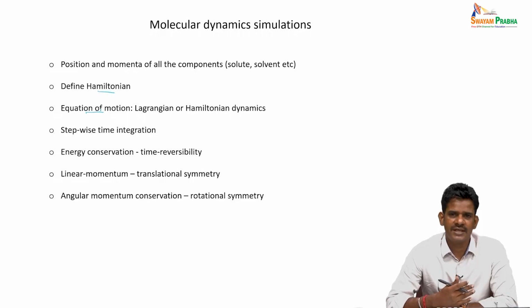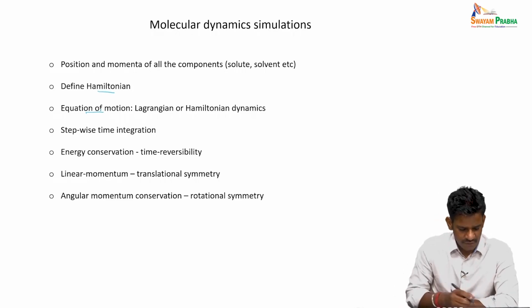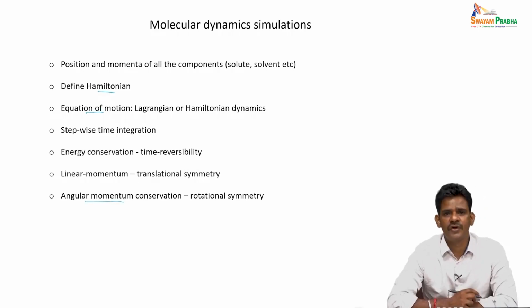However, we noted that in MD simulation, we have to deal with a finite number of particles, thousands, 10,000, 1 lakh, etc. To manage such a small system size, we have included certain concepts, namely periodic boundary conditions, potential cutoff, etc. Because of the implication of periodic boundary conditions, we also showed that the angular momentum will not be conserved.